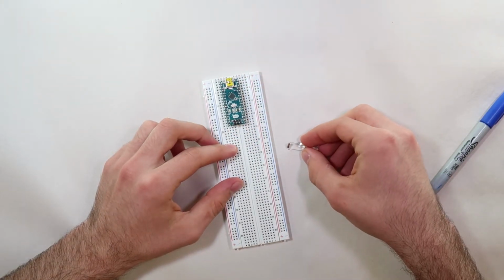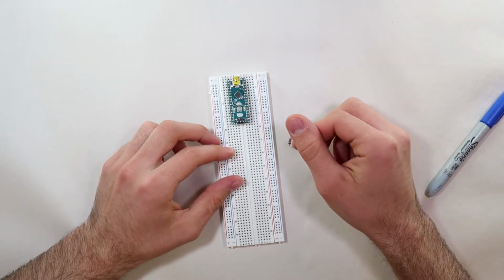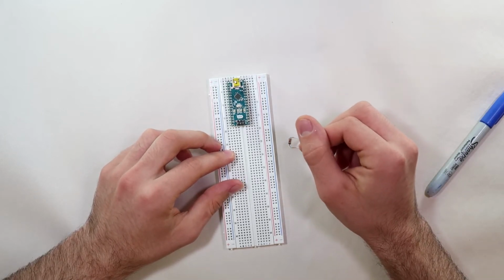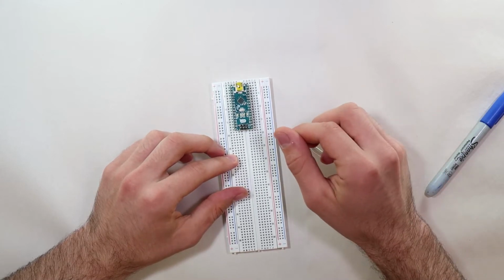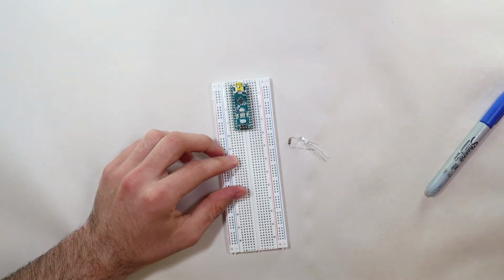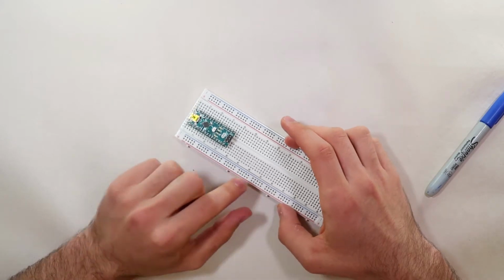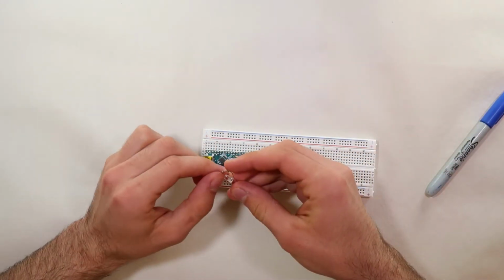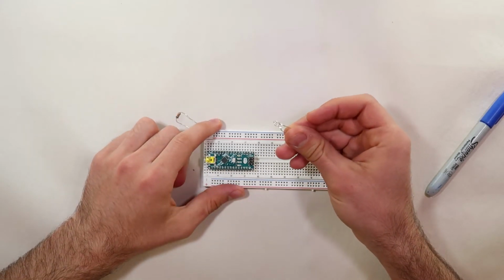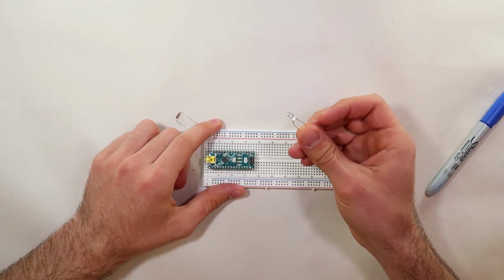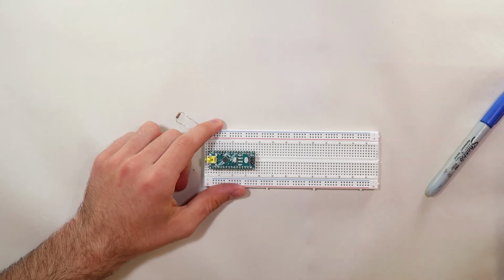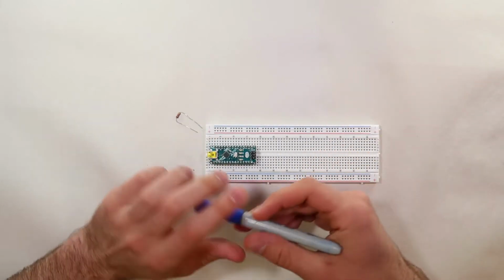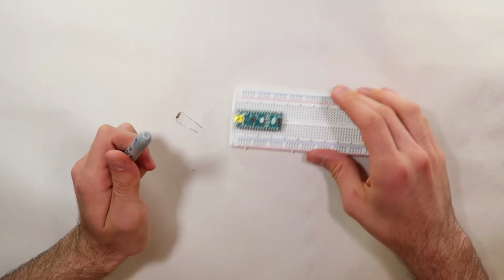In this case, we're going to talk about how to use pulse width modulation, which is a technique that you can use to control the power supply to a variety of different electrical devices. PWM can give the appearance of dimming and brightening an LED light, where before we were only able to supply a constant 5 volts or 3.3 volts from the Arduino Nano. And in our case, we'll be able to simulate different brightness levels in between 0 volts and 5 volts, and I'll show you how that's done.